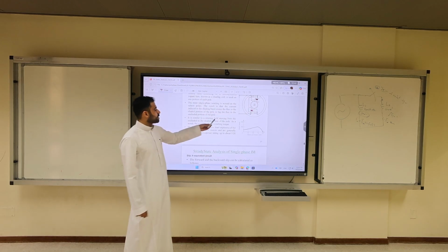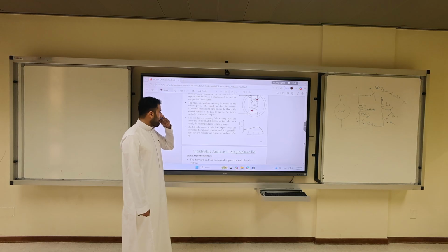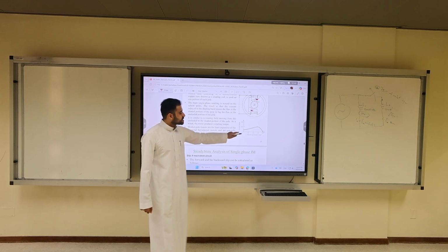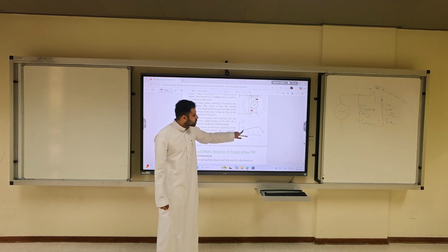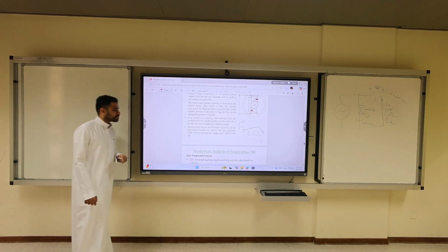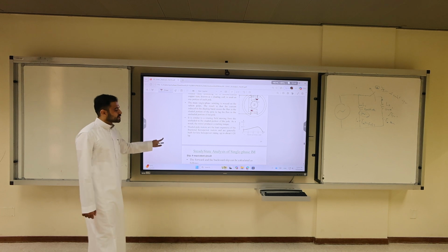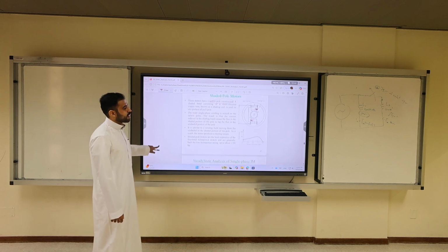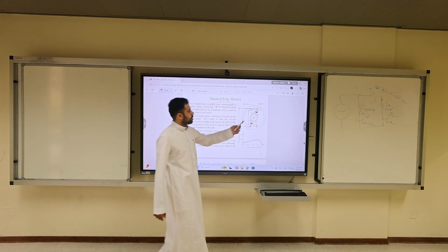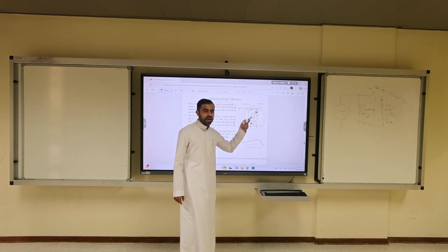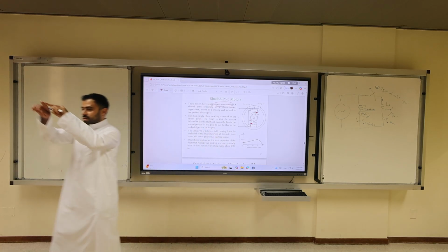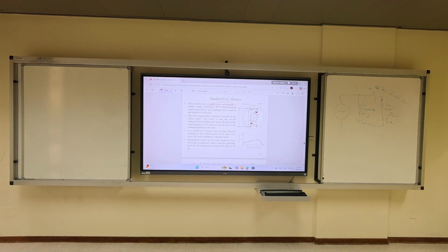It is similar to a rotating field from the unshaded to the shaded, but the motor now has a starting torque. If you don't have the shaded pole, you start from zero. So your shaded pole is just to give the motor a little kick at the start. However, this motor is not really used in real life much because it has a salient pole, so you have a dedicated structure type. It's better to use the smooth air gap without salient poles for manufacturing reasons.